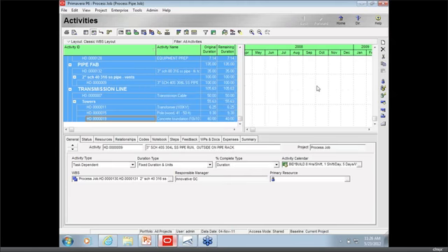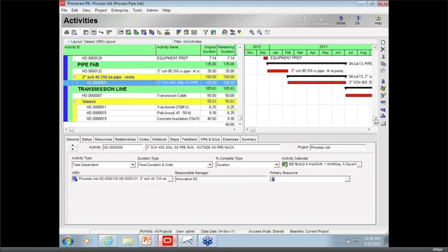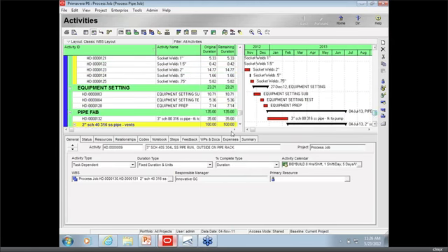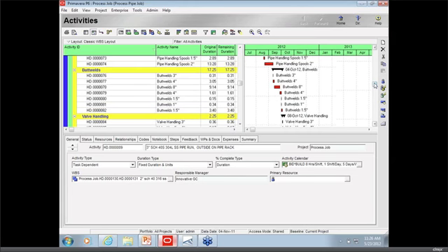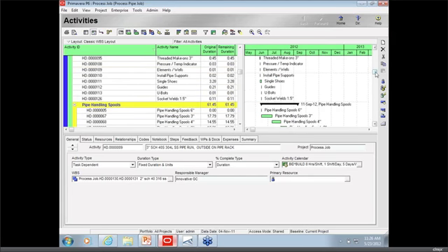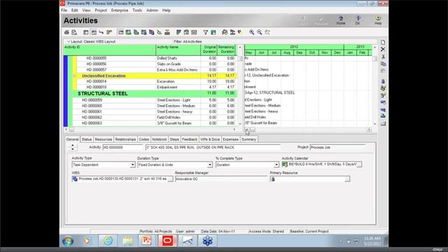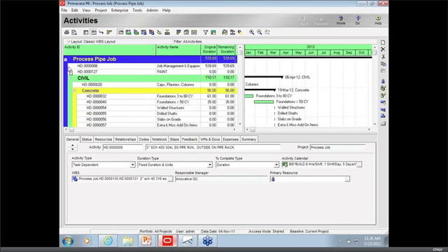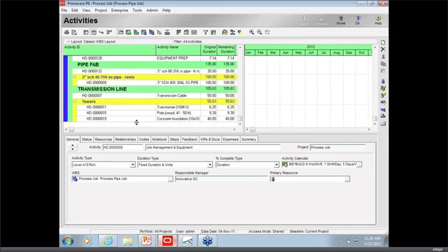So I'm going to quickly schedule this, and instantly we have a new schedule with start and finish dates, as I can easily scroll up and see, going to the very top. But more importantly, that first item for job management and equipment now has a duration assigned to it that's contingent on the schedule. We're going to start paying that project manager and operating engineer when this CAPS item starts. It's going to end when we finish that concrete foundation.